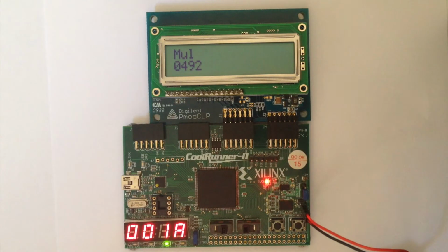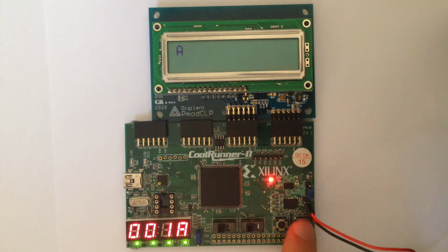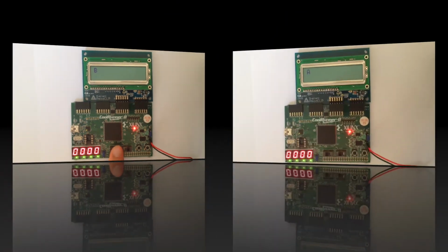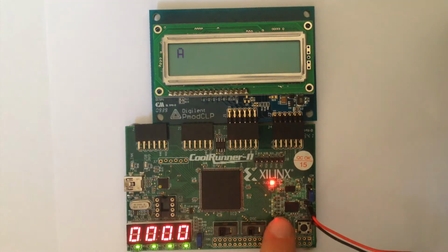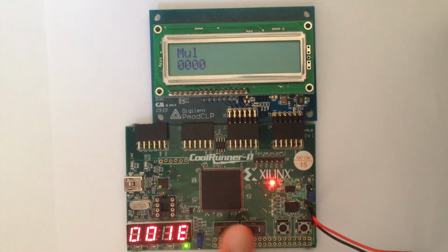Compute the sine function. Let's first reset the 2 operands, and to do so we go back into the operand mode, and switching all the LEDs on, and then pressing the right switch, we are able to reset the two numbers. Let's compute the sine of 30, which in hexadecimal representation is 1E. So let's change the 2 digits, the second to 1 and the first one to E. And then going to answer mode and then to sine, we get 0050, which is 1/2 without a decimal point.